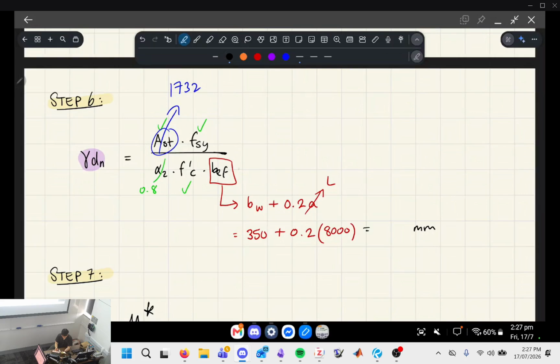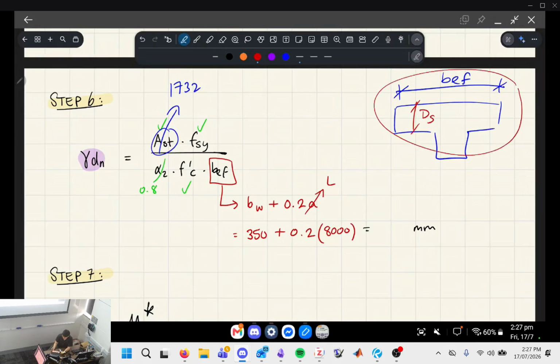We just have to calculate BEF. So what is BEF? In a T-beam, BEF is the effective width of the flange. The idea is that the T-beam, or just like the rectangular beam, picks up a bit of strength from either side due to the slab being attached to it. So this is actually the slab, but the beam itself, instead of just having the strength of the rectangle, has a bit of strength being contributed on both sides due to that slab. And the formula follows this, okay?